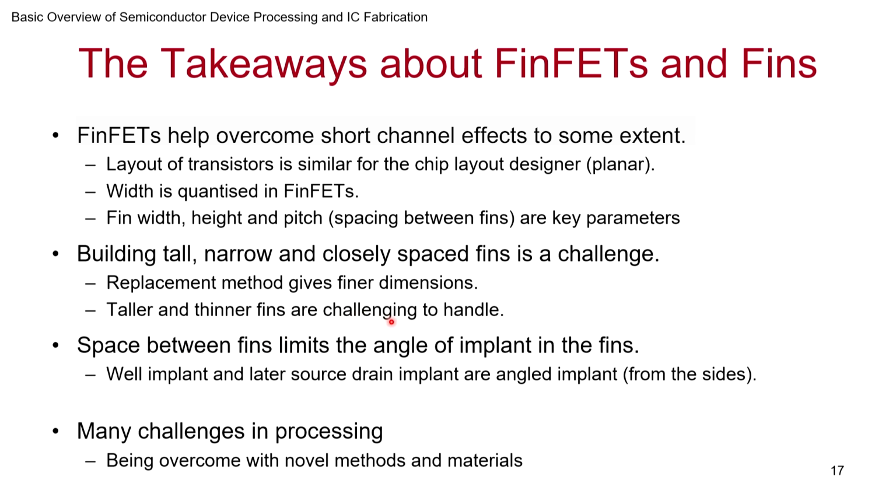They are difficult to handle, but the various fabs are handling them, and they are able to reproducibly make them. It's amazing that they are able to do it, and hats off to them for their ability. The space between fins, of course, ends up being limited. We can maybe make it smaller by bringing more creativity, but some subsequent processes matter, for example, the angled implant to form the source drain, or to form the well implant first, and then after the gate poly is put, to make the source drain also, you need to do an angled implant. It has to be possible.